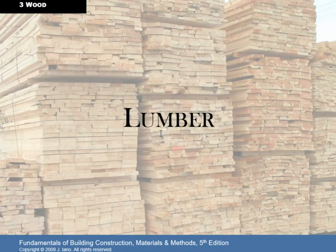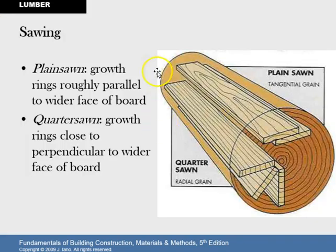Okay, moving on to lumber. All right, so this image we saw in my presentation, we talked about the difference between the plain sawn and the quarter sawn. This is the nice, the annual growth rings are coming in at 90 degrees, providing us with the premium, very stable lumber, as opposed to plain sawn, where it's tangential and prone to cupping and prone to warping much more.